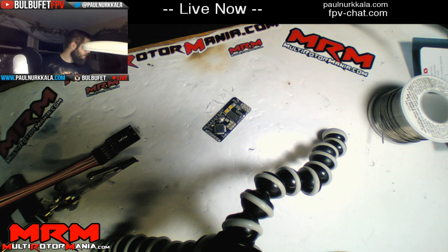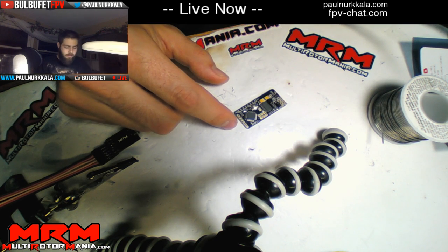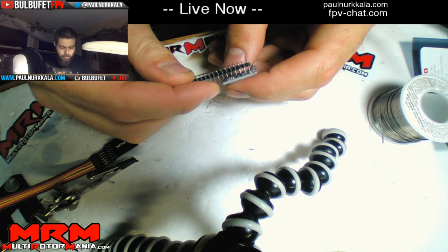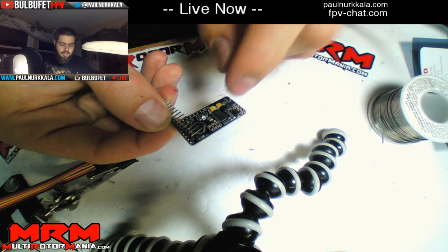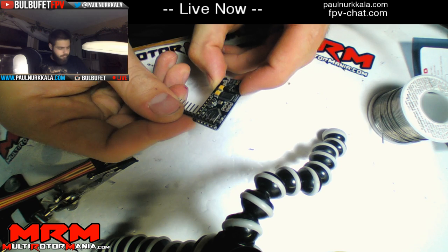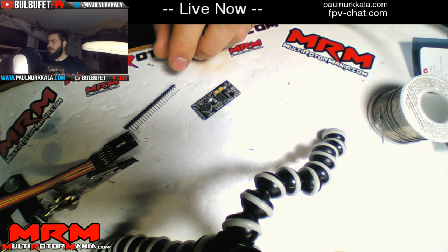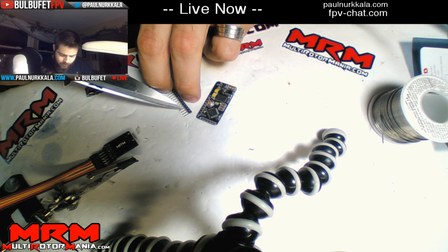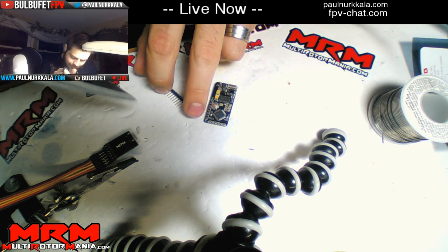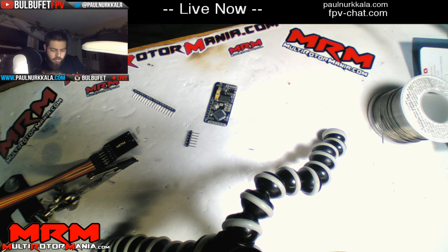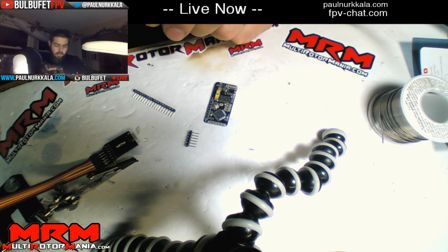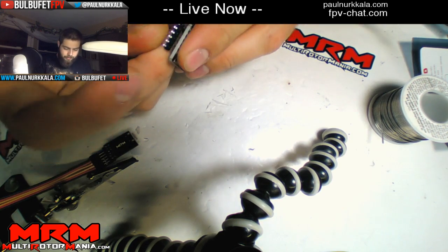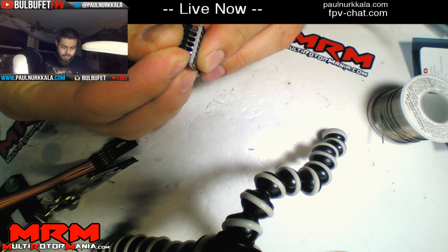But what we're going to do is take a single set of right angle pins and point it back across the board so that you can still plug it in and it takes up less space. So if I grab my scissors again, 1, 2, 3, 4, 5, 6, and let's cut. And then this will fit on here, kind of facing backwards across the whole board.